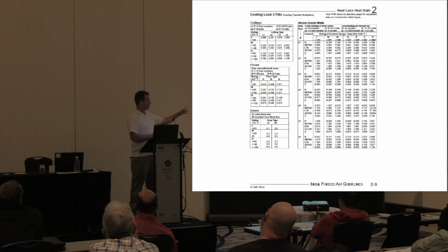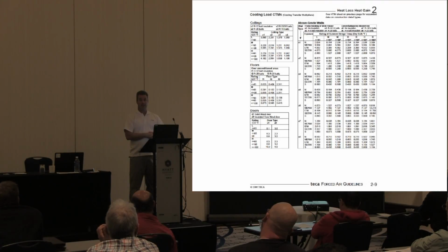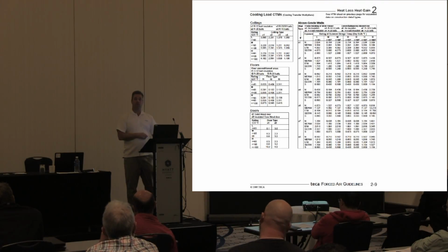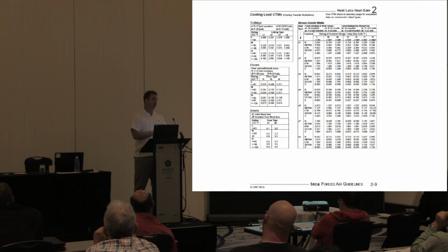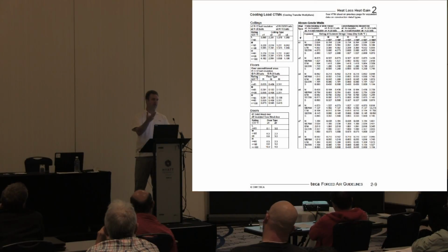What they should be doing is figuring out at what temperature that heat pump won't have the capacity to maintain the temperature in the house. That's what we call the balance point for switchover, where you have to switch over to make sure that the house stays at 72 degrees. So make sure the guys you're dealing with understand that there is a magic temperature and they should be putting a system in. We used to have to put kits in, but now the thermostat and control systems deal with it for us, so we don't have to do those anymore.